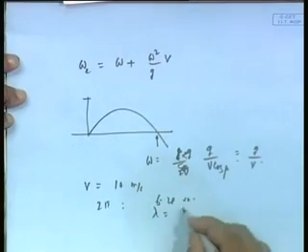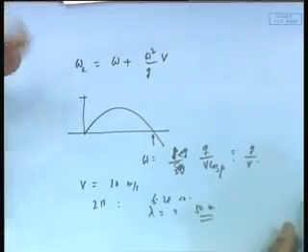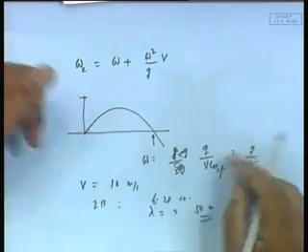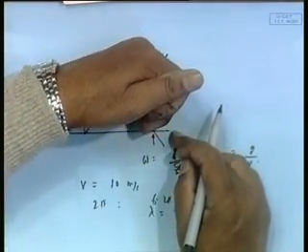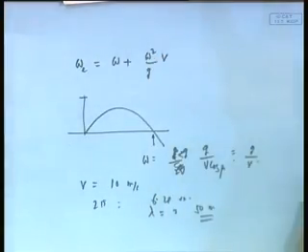1.56 into 6 square, that is approximately equal to 36 into 1 and a half, about 50 meter. So you see, for a 50 meter long wave, for this particular case, you end up getting 0 encounter frequency in a following wave. So it is a very feasible range. That means a 50 meter wavelength is possible, and there can be a small frigate going at 10 meter per second. So in other words, realistic waves do exist coming from following directions, which can lead to negative encounter frequency, which can lead to 0 encounter frequency. It is not outside my practical bound. This is important, which means I cannot ignore it if there is a following wave coming. It is a practical scenario. Waves are there 50 meter, 100 meter, 200 meter, etc.